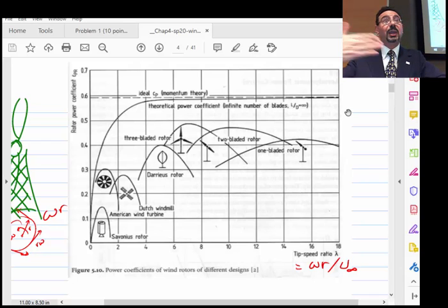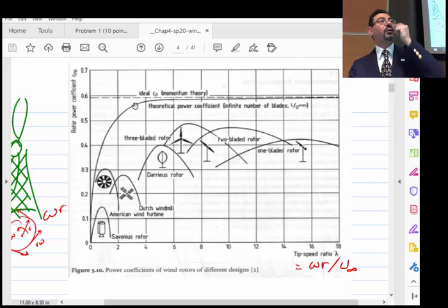That Pelton wheel, if you make it at 180 degrees, you get 100% efficiency on paper. Yes, there is some friction, but this is also on paper. We didn't even talk about the friction on the rotor and the plates and the wake, right? But why is this 59% and the other one 95% or 100%? What's bad about the wind turbine that it cannot hit 100%?